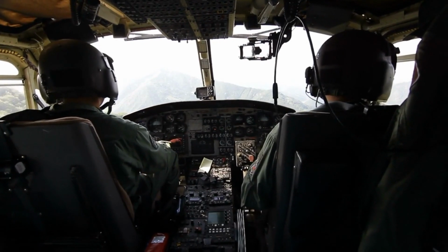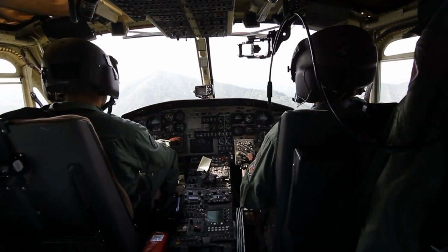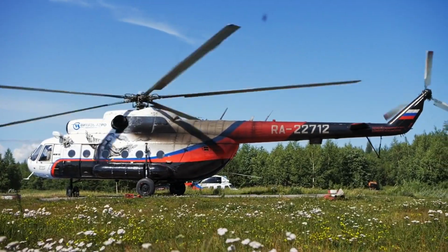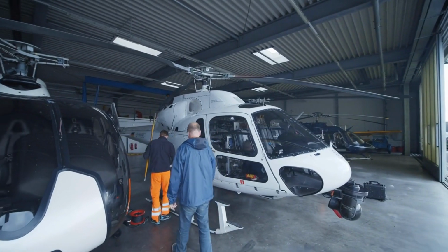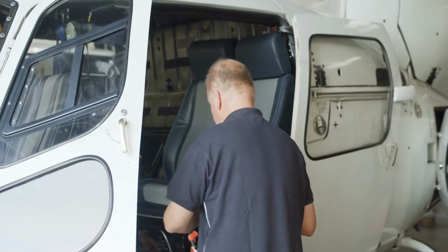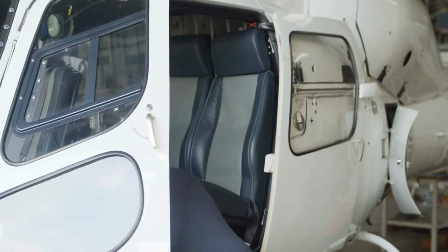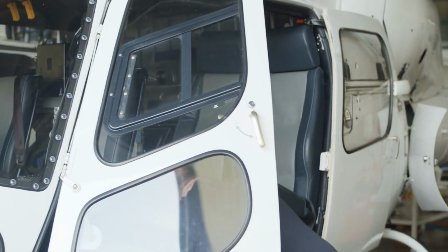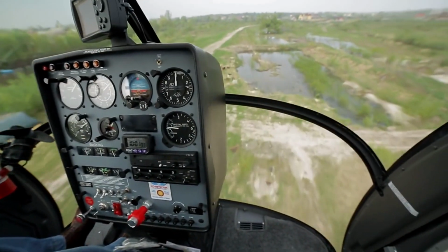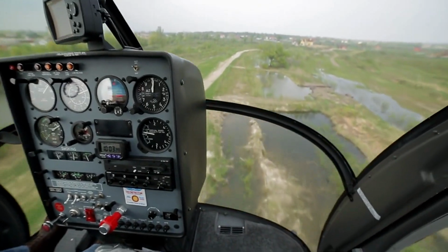In this aerial ballet, the pilot's technique is of paramount importance. To sustain a hover over a point, keen observation is essential. Utilizing side view and peripheral vision, the pilot identifies subtle changes in the helicopter's attitude and altitude. Small, coordinated corrections are then made before any noticeable movement occurs, ensuring a seamless hover. It's crucial to maintain a primary focus at a distance from the aircraft, preventing overcontrolling. The collective and throttle govern altitude and RPM, while the cyclic and pedals control the helicopter's position and heading.